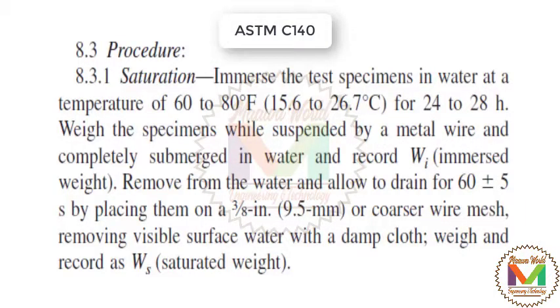As you can see, according to 8.3 procedure, we have 8.3.1 saturation. We have immersed the three specimens in water at a temperature of 60 to 80 Fahrenheit, or we can say from 15.6 to 26.7 centigrade, for 28 hours.